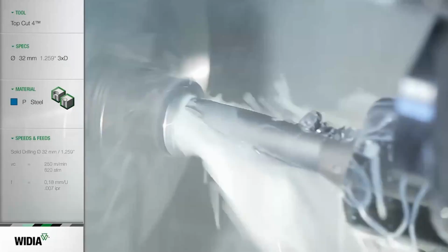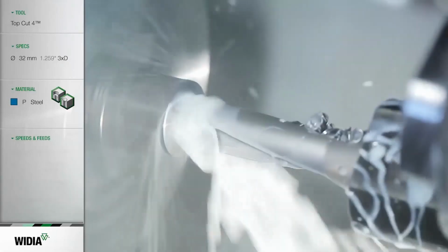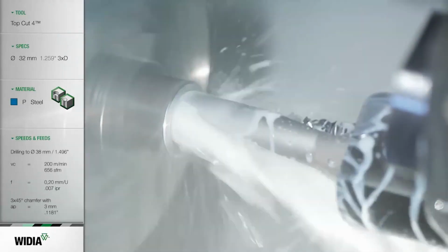You could hear some noise, but it's very normal noise. Noise is not normal when it is irregular, when sometimes it has one sound, then another sound, then no sound, and again sound. That means there's something strange with the chip formation. Here it's a very normal process, like we can see now. So we produce the hole in the first pass, and then we move the drill in the direction of the periphery insert, and then make the internal turning operation.